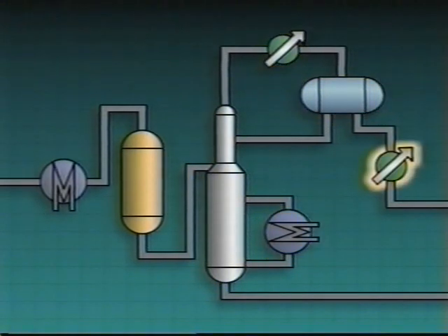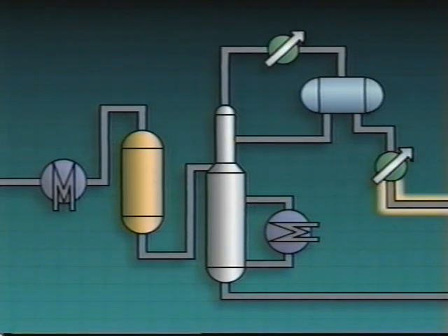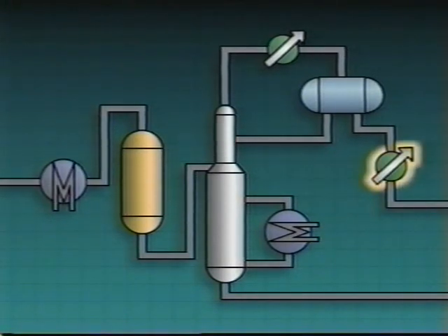But once we reach the condenser, the water leak is going to contaminate the product. This contamination can be discovered through sample testing. When this abnormal condition is detected, we'll know we've pinpointed the problem to this condenser. Checking components in a process one at a time in sequence is sometimes called the serial method of troubleshooting. This method is logical and effective, but depending on the problem and on the process, it may be time-consuming.